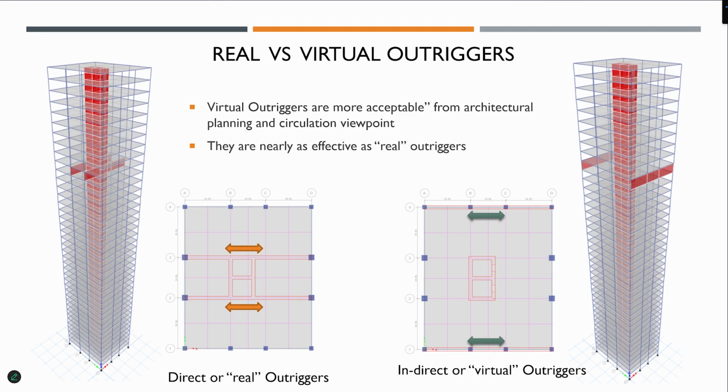Some columns will shorten more and some will shorten less because the forces are so much different. So you end up with the problems anyway. Either you match the size of the column with the axial force, or you put in more reinforcement, but the deformation cannot be controlled by more reinforcement. Which means that when you put this belt here, it also distributes the force to all the columns equally because of its stiffness in that direction.